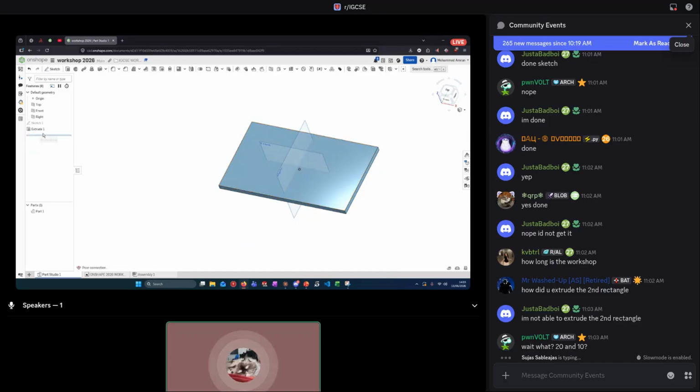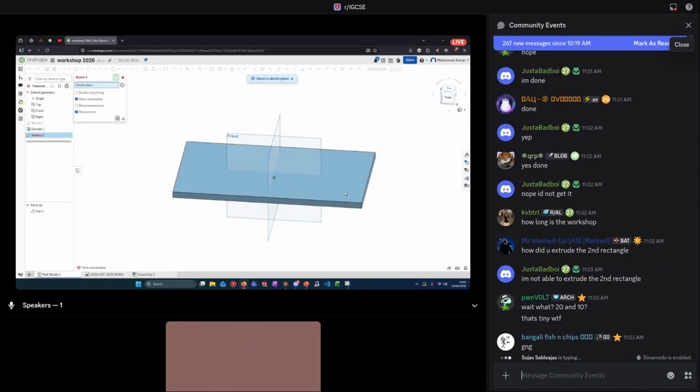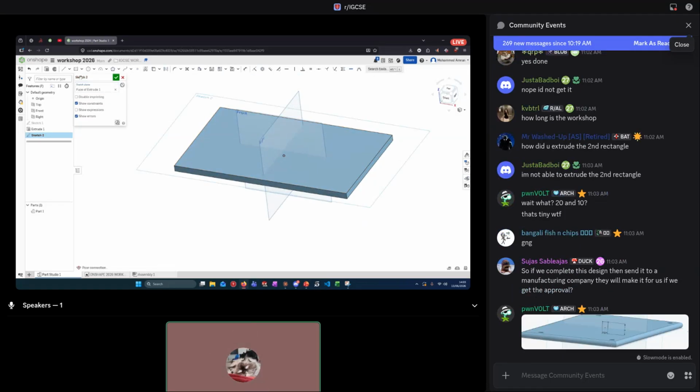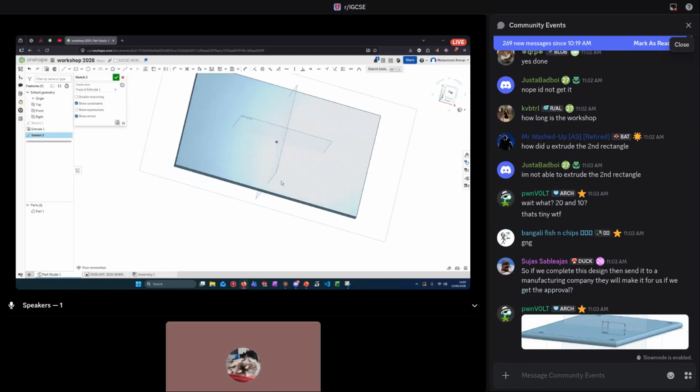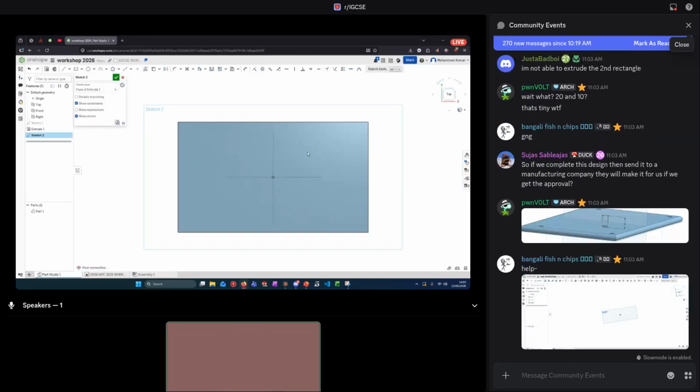I'm going to go through this again real quick. Okay, so first I created a new sketch. Sketch on the top of this rectangle. Once I click the top, I enter the sketch. And then I click the top, so I'm viewing the part normal to the face.